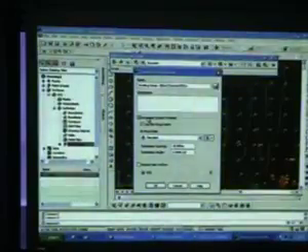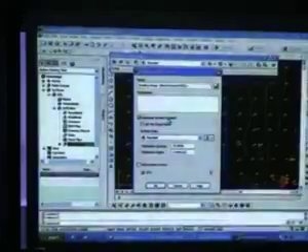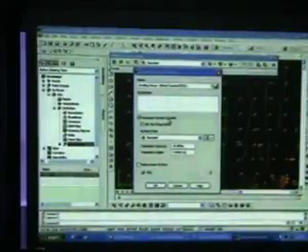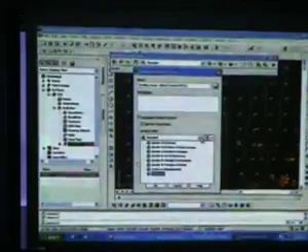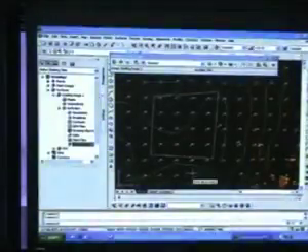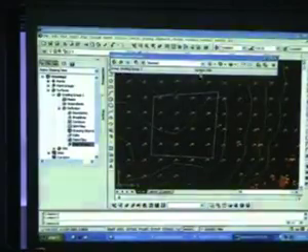If you like, you can create a surface automatically. Instead of creating our own surface called proposed level, you can say I want to use this grade, and just click automatic surface creation. It will create a proposed level for you automatically from this grade. The name of the platform will be called grading group 1, so that's why we say use group. Surface style, you can also give it a try later. I'll just leave this as standard first and click OK. So this is the surface, grading group 1. You'll find now that we have grading group 1 and the surface is OGL.